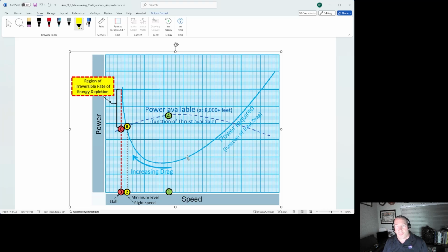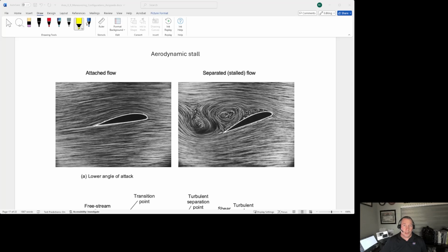When we get into Area of Operation 10 Bravo, we're going to talk about how you can fly yourself from one side to the other of that same setting without touching your power. Stay tuned for that. Well, that concludes our section on the aerodynamics of slow flight, stalls, and everything that we covered. Keep these concepts in mind at all times. Remember about the region of reverse command, and recognize what happens and what you have to do. You've got to add power to fly in that region.